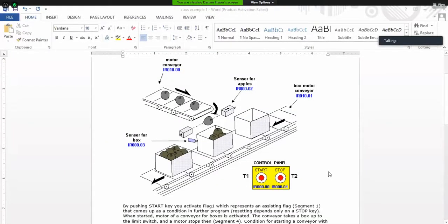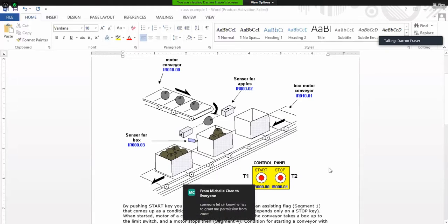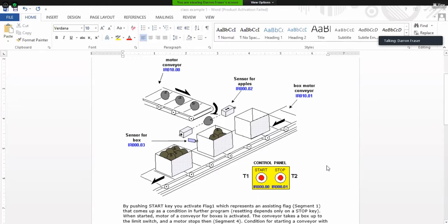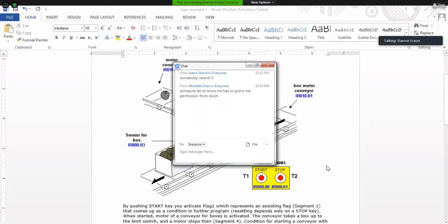All right. So the inputs are any switches or sensors that we have to detect anything. And the output is any motor, light, any actuator, any valve that we have to open or close. Anything that, when you put current to it, it turns on or does something, and does something else when current is not going to it. So anything that you have to actuate, turn on or off, is an output. Any switch that will switch on, or a sensor or a switch that detects, is an input. And then we talk about the states after that.